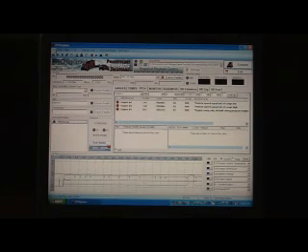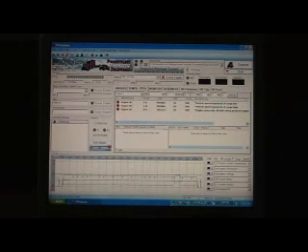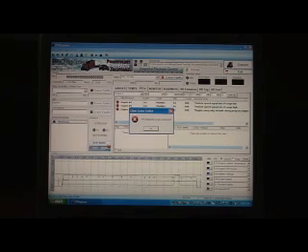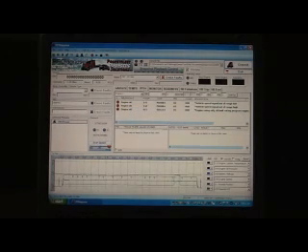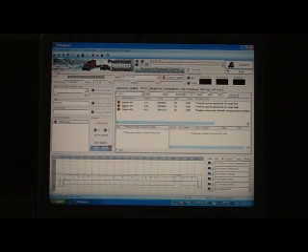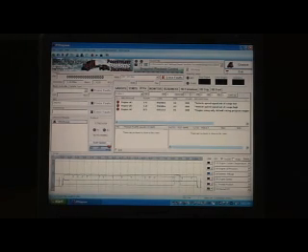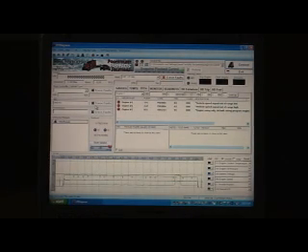You may also select the Erase All Fault Codes button. You would select the icon that resembles a pencil eraser, and that will erase all of the faults in all of the modules in this particular vehicle. Please note, if you erase all of the faults, including ABS, your ABS warning light will illuminate until the vehicle is driven. This is a normal condition. Do not be alarmed.